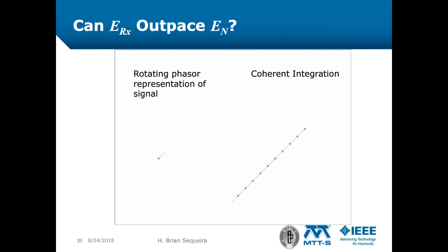One answer to that question is periodicity in conjunction with stroboscopic sampling and accumulation, as depicted in this slide. A periodic voltage is conveniently represented in the complex plane as a phasor that rotates about the origin. The time in which the phasor completes one rotation is the period of the signal. If this voltage is sampled every period or integer multiples thereof, samples of the phasor appear stationary, much the same way by which a rotating object appears stationary under a strobe light.